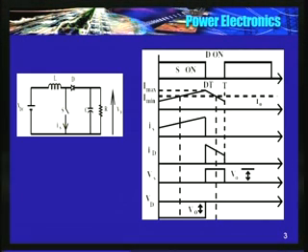So here is the circuit. Switch is on for D into T duration, and from DT to T, the diode D is on. So current increases from I min to I max, and from I max to I min it decreases from DT to T. So when I close the switch, the source current or the inductor current is the same as the switch current, IS. I am representing IS as the switch current. I might have said IS is the source current in the buck converter, maybe this doesn't matter, but here I am saying IS is the switch current.